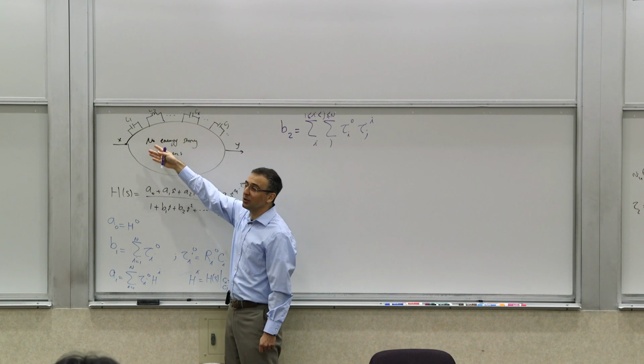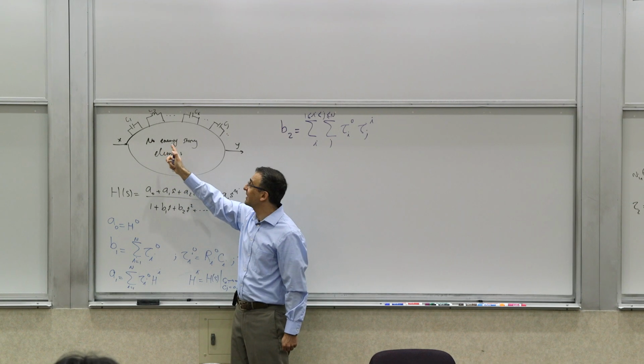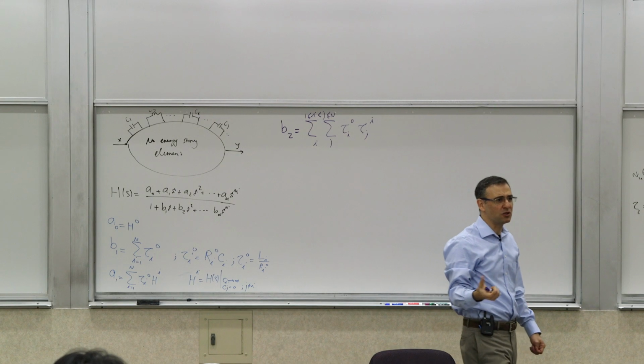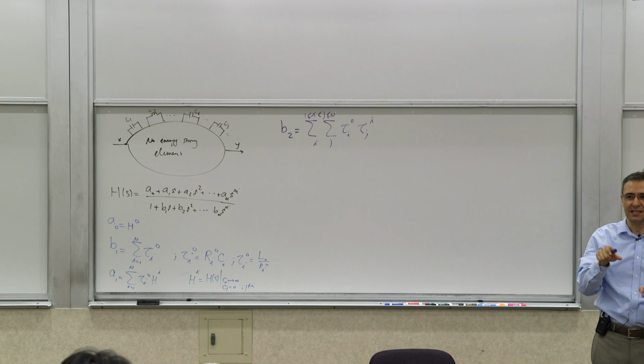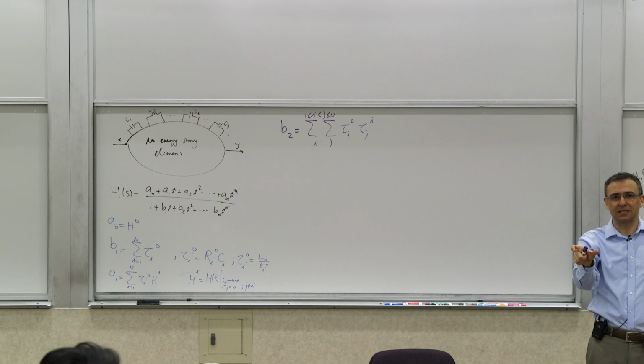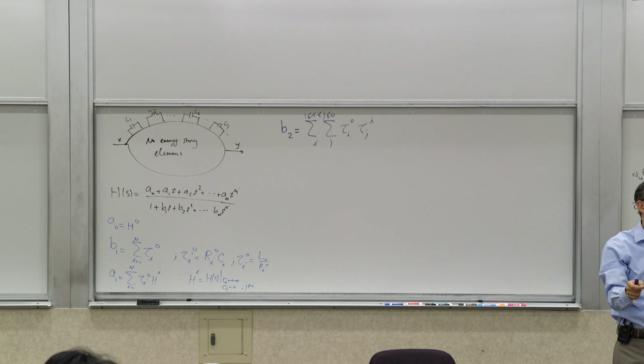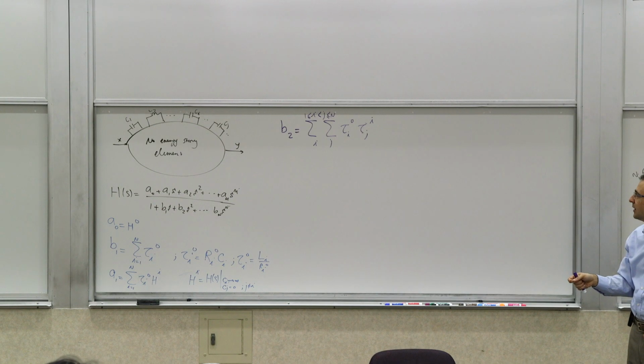So it's very similar to the zero value time constant, except for the fact that now element i is infinite valued. In the case of a capacitor, it's short-circuited. So you do the similar calculation, except now instead of keeping Ci open, you do Ci short, and you see what the time constant is. I haven't proven this yet. We haven't proven this, but yes.